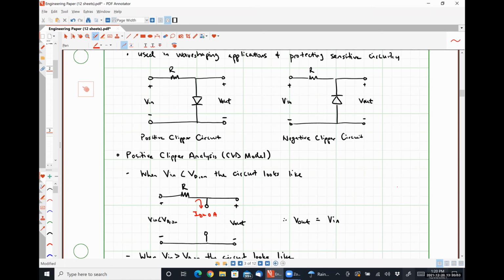We can make all kinds of funky wave shaping things by putting a green LED for one diode and a red LED for the other, because they have different VD on values. They offer us asymmetrical clipping, which gives us a different sound than you would get with symmetrical clipping or a pair of 1N4008 diodes or whatever.